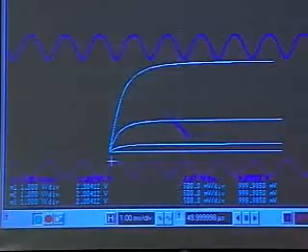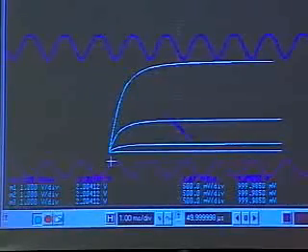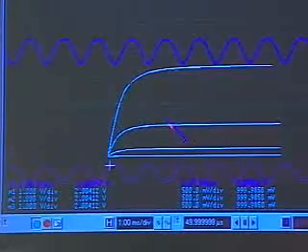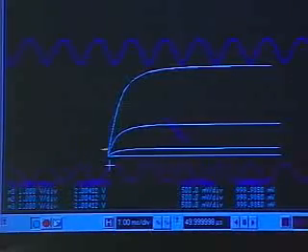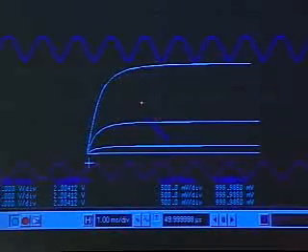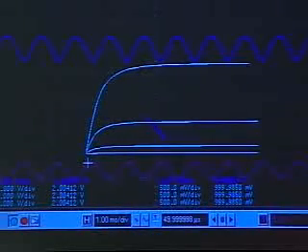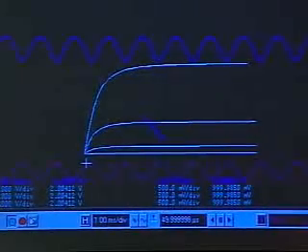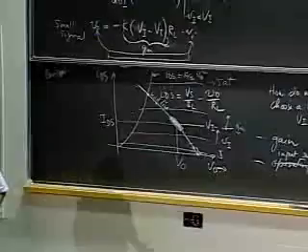Okay, let's leave it here for a moment. This is the region that we're looking at. Let me increase the bias. If I increase VI, what do you think should happen to this line here? Well, if I increase the bias, the line should go up, right? Because remember the dot is in the middle of this thing here. So one is that the line moves up. Do you expect anything else to happen to that line? Pardon? It increases, exactly. If I increase the bias point to here, then this must also increase because my gain is increased. Okay, let me do that.